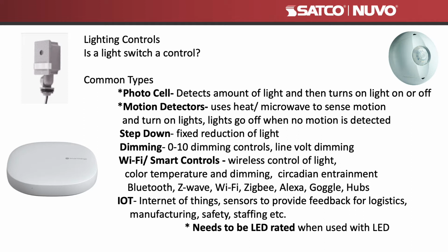With a control, when a worker goes into the aisle to do some picking, the motion sensor will pick that up and turn the lights on. When the worker's done picking in that aisle or in that section, the motion sensor will detect no motion or no presence and will turn the light off. It helps to control the cost of lighting and reduce its use.